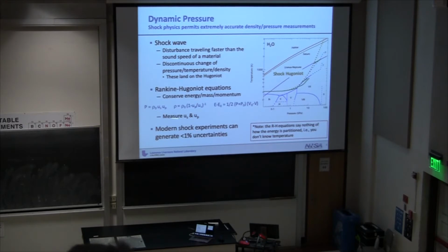But the nice thing about that is because you have these three conservation laws that are in here, they're written in terms of shock speed, basically sample speed. So this is your impact speed. This is how fast your sample goes, the initial density of your sample, the density you get to, and the pressure you get to. And you have 3 equations here, and you have 5 unknowns. So you just have to measure 2 things to get all of those things done.